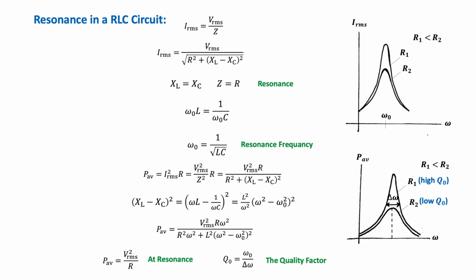This frequency is also the natural frequency of oscillation of an LC circuit, as we have seen previously. Therefore, the current in a series RLC circuit reaches its maximum value when the frequency of the applied voltage matches the natural frequency of the circuit. When it matches, we have maximum current, or resonance. Also, at this frequency, the current is in phase with the applied voltage.